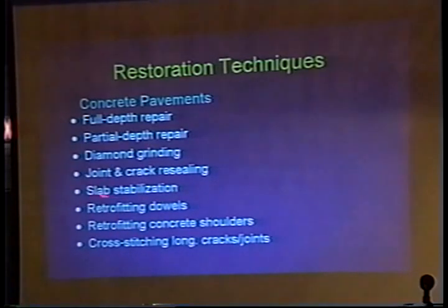Slab stabilization, where you pump a pozzolan grout or some similar material to fill up the voids underneath the pavement that might be occurring, to give uniform support to the concrete pavement.